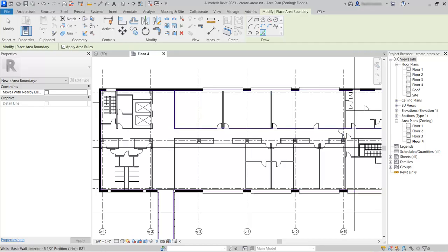And then we'll also select the wall at the end of the corridor to close off the corridor here. Now we want to close in the other side of the corridor, but we don't actually have a continuous wall here to select, so we'll draw this one in a moment. Whilst we have the Pick Lines tool enabled, we'll pick on the wall at the left here that comes back to the external wall, and now we'll go up to the Draw panel on the ribbon and enable the Line tool. And now we can draw that line across the corridor to enclose that space.